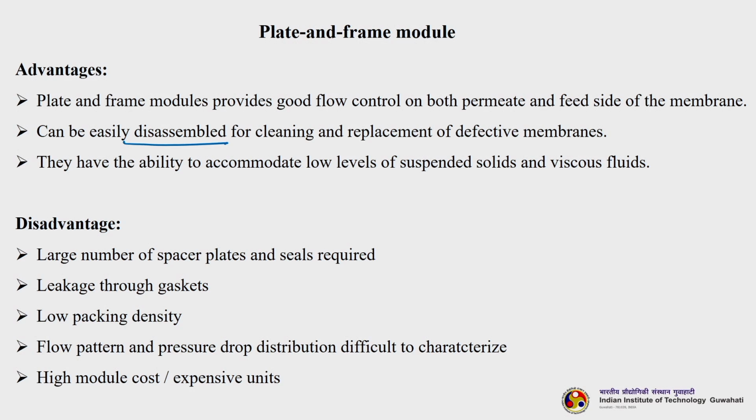They also have the ability to accommodate low levels of suspended solids and viscous fluids. This is important because many times the levels of suspended solids may be very low, and other module configurations may not help. In that case we can use the plate and frame type, and if the feed viscosity is very high, then we can also use the plate and frame module.